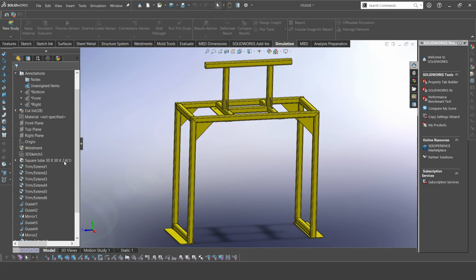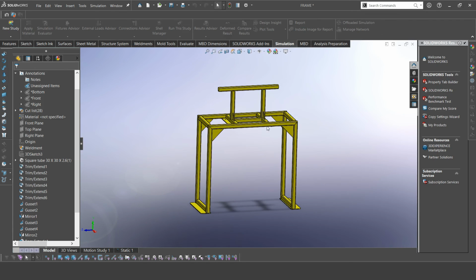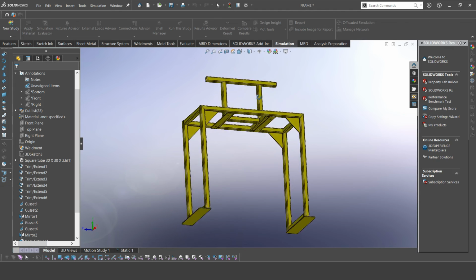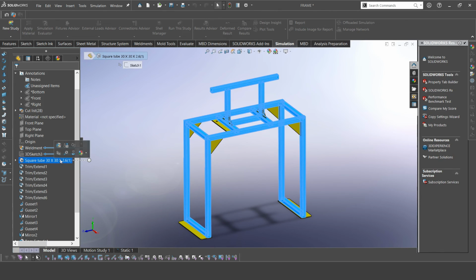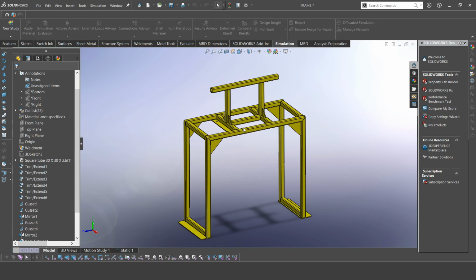We can use 35 and see, and yeah, it will be better. Okay, so a stronger frame, if we have this larger pipe, maybe a larger section, this means that our machine will actually last longer. Okay, and these gussets here, we have seen that they take up the stresses, so this will help us have a longer life for our machine.